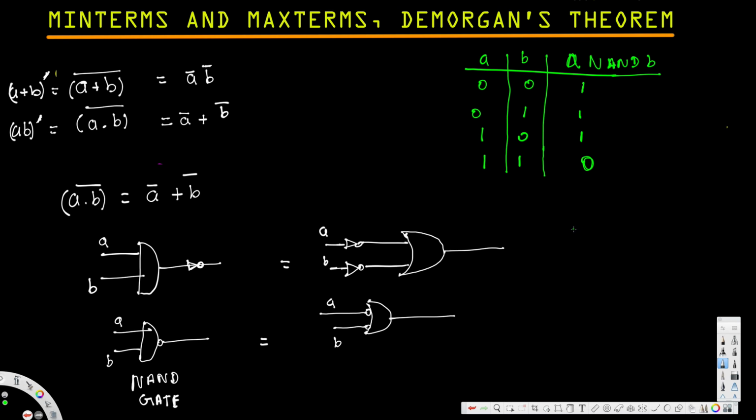Now let's look at a circuit. Can we replace this NOT gate with the NAND gate? Can we do the same thing we did before for the NOR gate? We can do the same thing. Like if you connect these two inputs together and put it like this, let's see what's going to happen. So this is a NAND gate. Now if you put a 0, that's going to split around 0, 0. And 0, 0 results in what? We will get a 1.